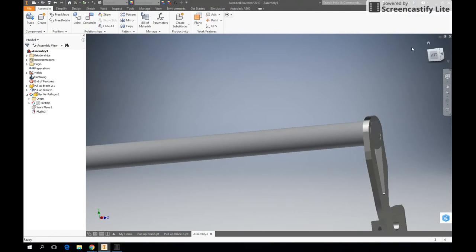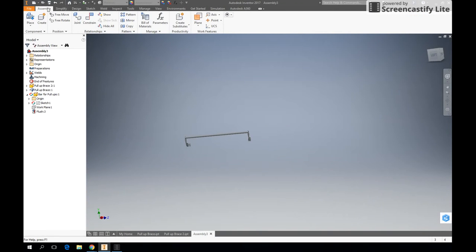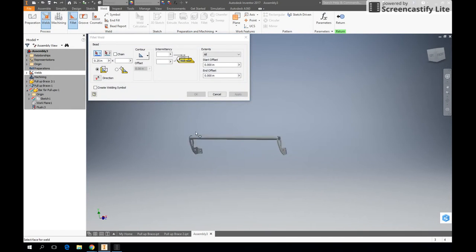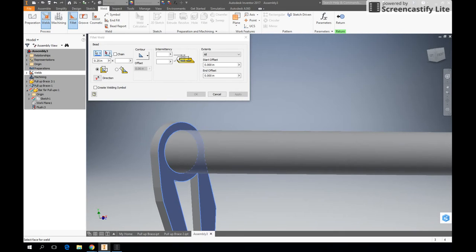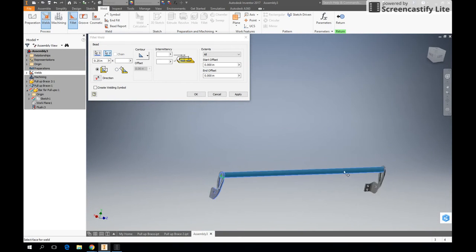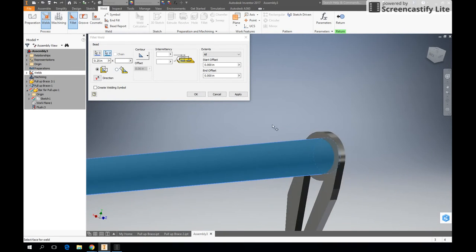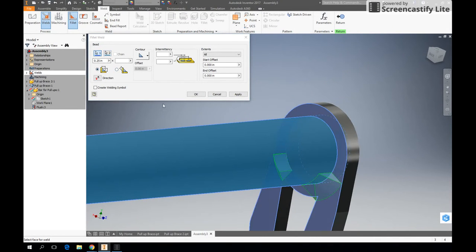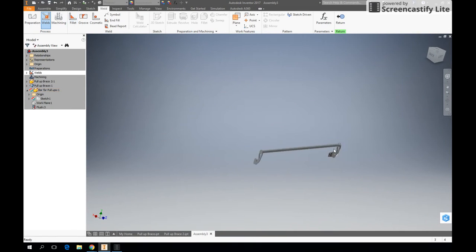Okay, now that we have our assembly, we can put our welds in. We'll hit Return, go to our Weld tab, select Welds, and our type of weld, in this case a fillet, and we can select which faces we want to weld. Select the bar and the bracket to weld together, and now we can change the size of the bead. In this case, looks a little big, we'll do a 0.125 weld. And now you can see our welds on the part.